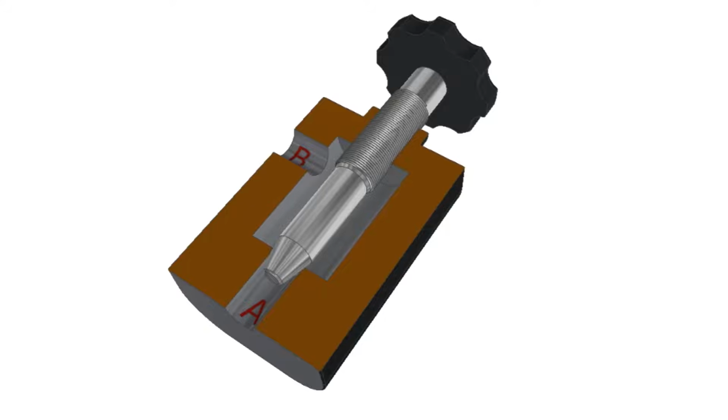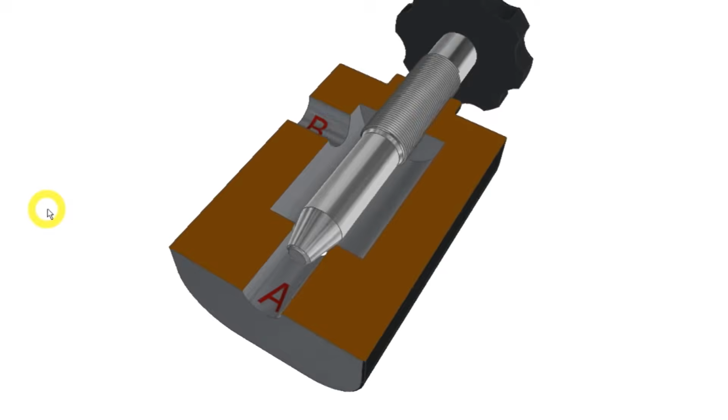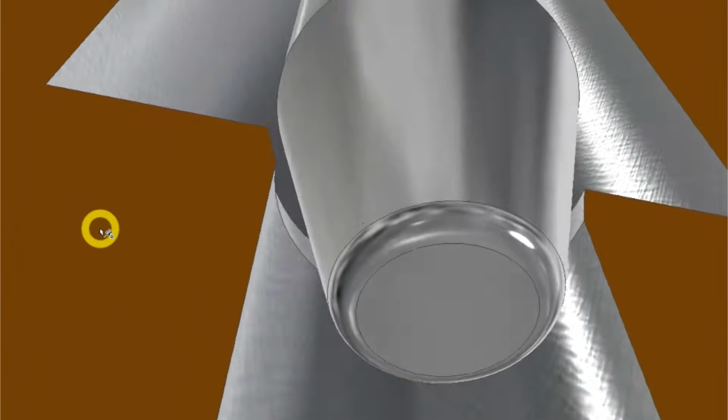Here I have made a drawing of the simplest variant of a choke valve. A choke valve creates friction, which steals some of the energy from the liquid flow. This makes it harder for the pump to press liquid through the system, and the speed of the liquid is slowed down. You can see that there is a small gap between the valve body and the valve plunger with this valve adjustment.